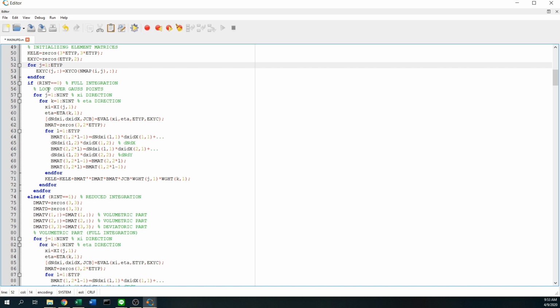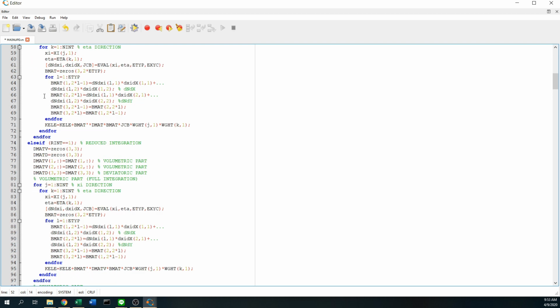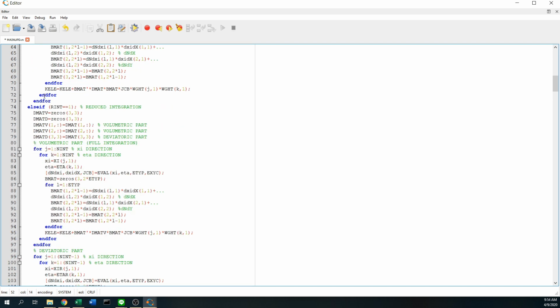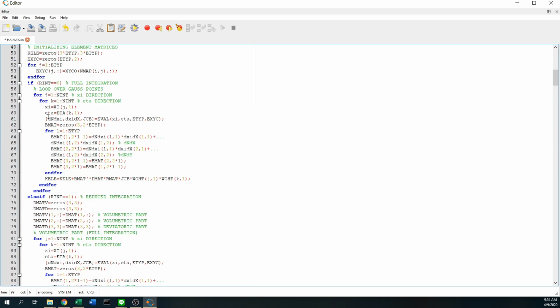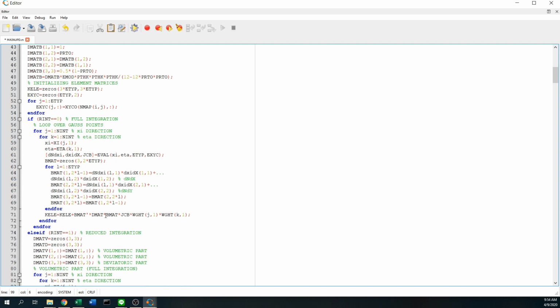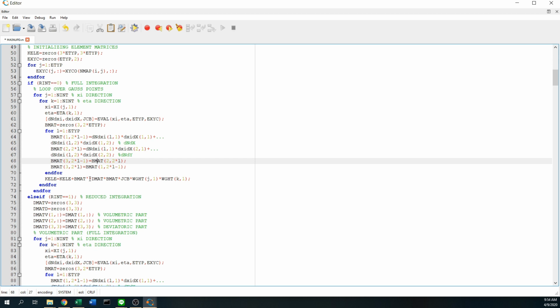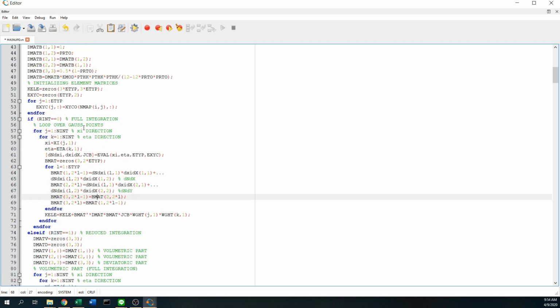The reduced integration actually can be conducted, but it will be on the shear part only, right? Actually, in the old code we can put the if for the shear part only. Yeah, it could be done this way, but it could be generalized. So we break the B matrix into the volumetric and deviatoric part as a default, and then the operation is just longer. Fine.